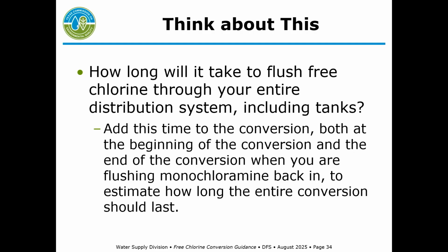So you probably have a pretty good idea that if we're pumping in this flow rate and we're flushing, we think we'll be able to get free chlorine through the distribution system in so much time. To that amount of time that you determine, add that to the time it takes to do the conversion. You want to add that time at the beginning and at the end, and make sure then you've got at least 2 weeks between the beginning and the end, like I said, so you're exposing all the points in the distribution system to free chlorine for at least 2 weeks. That'll give you an idea of how long your free chlorine conversion needs to last.